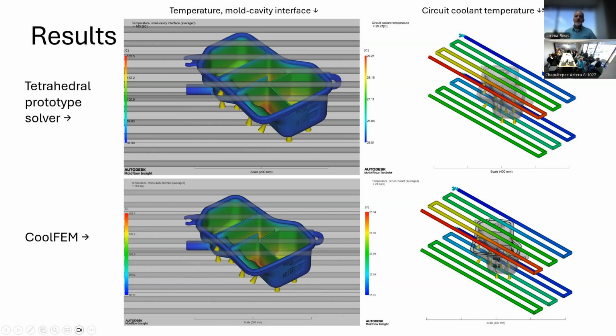This is going to be an area that has to grow. The initial release will most likely be contained to simple models, simple geometries, and no inserts, no sliders or whatever, just a basic Moldflow analysis in a sense. So cooling channels, beams, runner systems, tetras and beams, and the part is tetras, or dual domain, I believe.